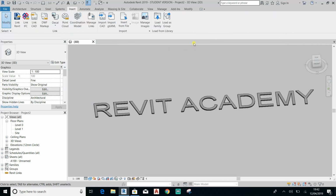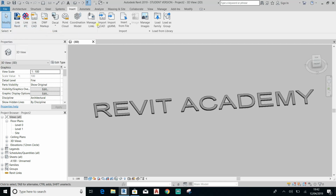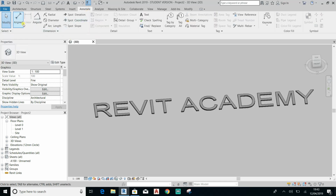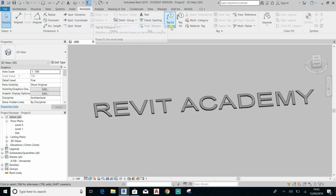The Insert tab, if you want to import an external file, whether you want to link it or import it, you would have to click on the Insert tab, linking the structural engineers' models, mechanical, electrical or plumbing models, etc. Annotate tab: all the dimensioning, all the detail lines, the filled regions, components that you want to add to your detail come from this tab here. You can add text, you can add tags to the doors, windows, once you've populated the information within the family itself.